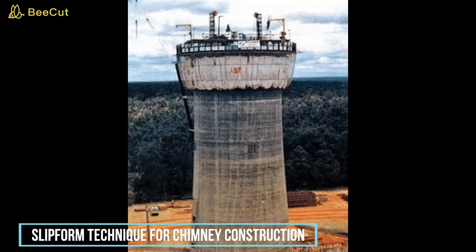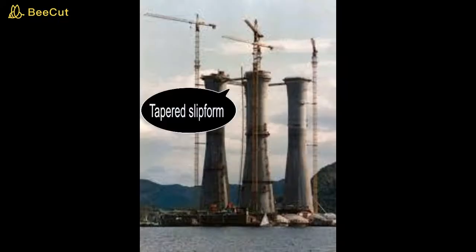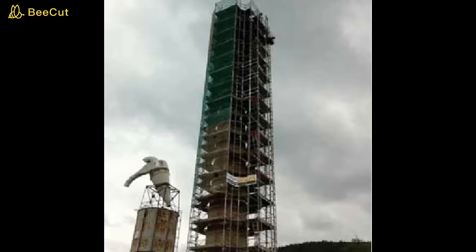Second, slip form technique for chimney construction. This slip form method that is used to build large chimneys, cooling towers and piers is called tapered slip form. This technique is used to create vertical structures of different wall thicknesses or shapes or diameters.